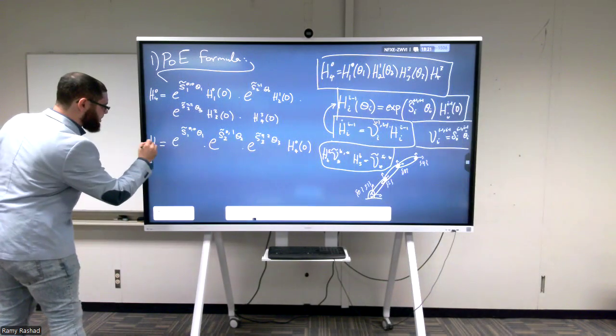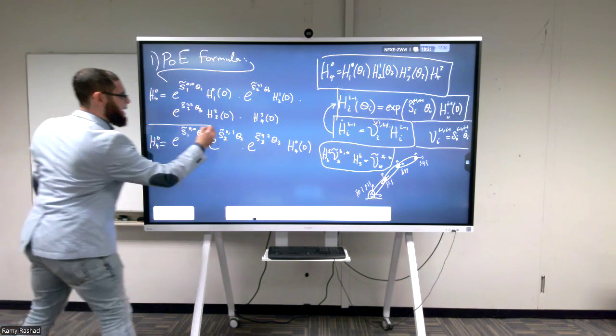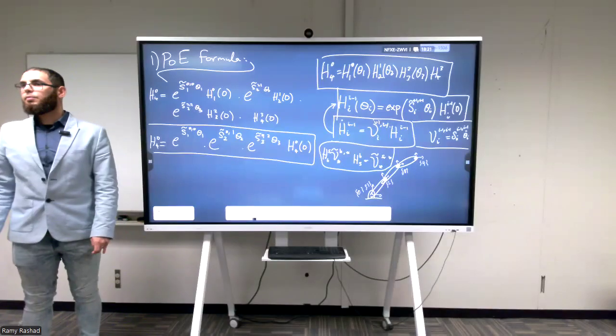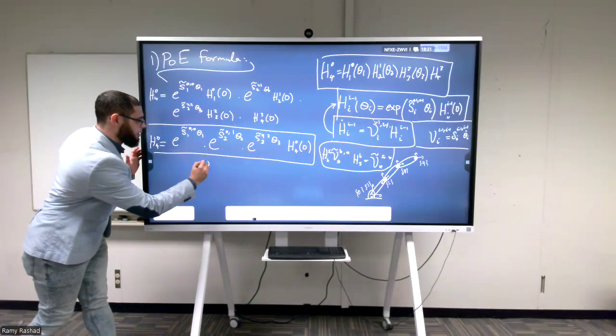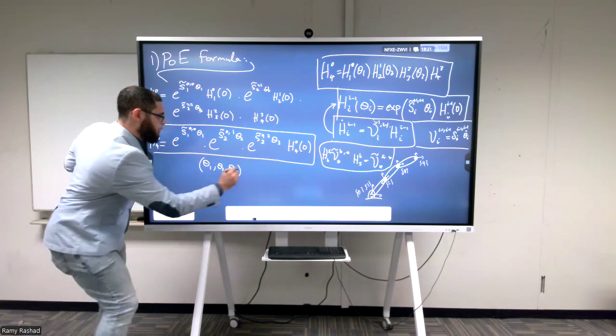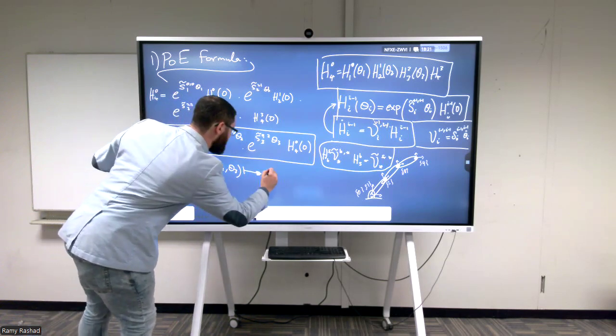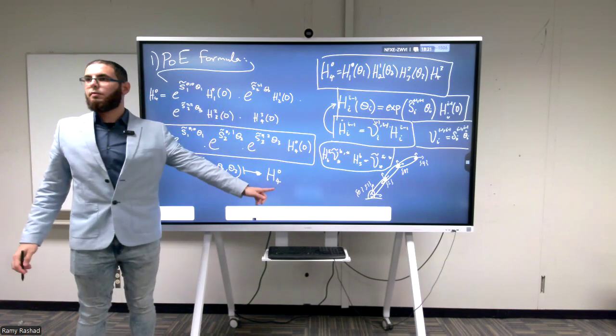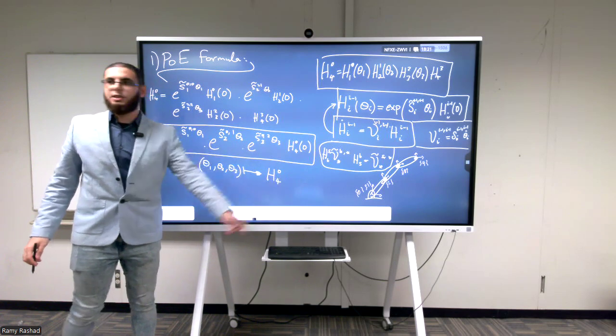So this expression is very powerful. And this is nothing else than the forward kinematics map, because this is a map that takes theta 1, theta 2, theta 3, and gives you, in the end, a homogeneous transformation that corresponds to the end effector pose seen from the 0 frame.